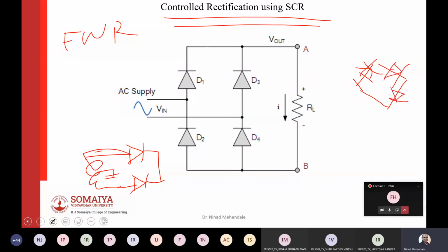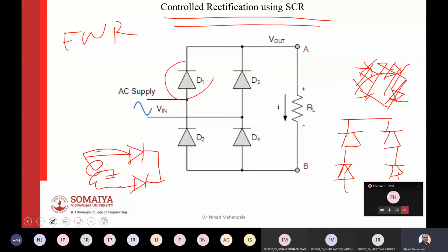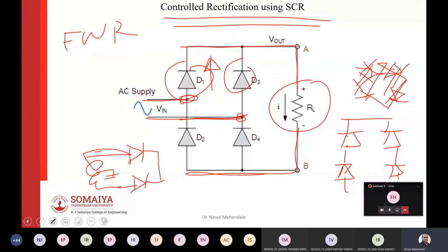So to simplify this, always draw a rectifier where all the elements are looking towards the top of the screen. So each and every element is always looking towards the top. You can see this diode, everyone is pointing towards the top. And then you connect your main source at the center, and then you try to measure the output across the resistor RL, and you should get your circuit output, that is the AC output, at that particular point.